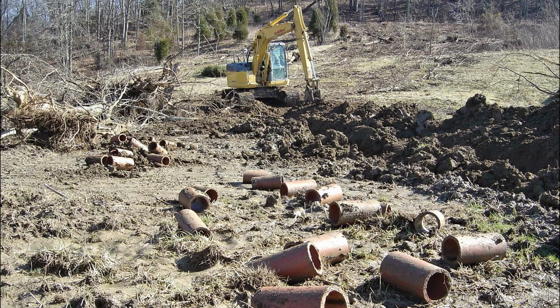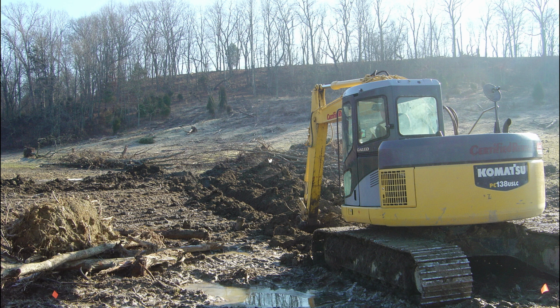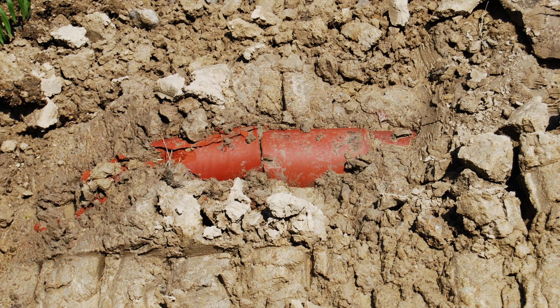Here an excavator operator is removing a buried drain line that's made from clay tiles. The ditch is going to be filled with soil that's high in clay, and that soil would be compacted using the bucket of the excavator. This is a lot like what we do when we build a groundwater dam. The entire drain line is being removed. This is the most reliable way of disabling a buried drainage system.